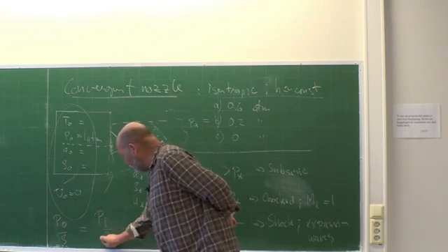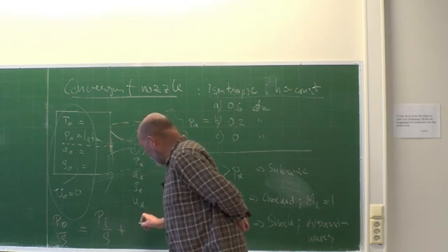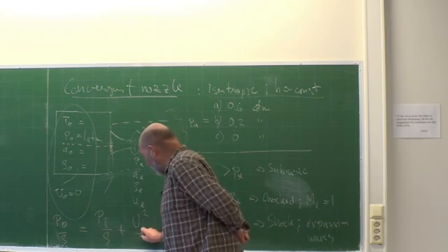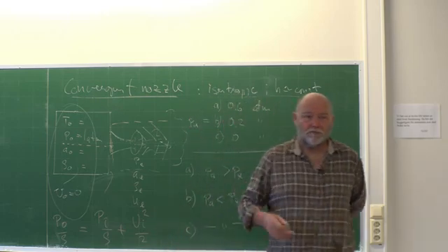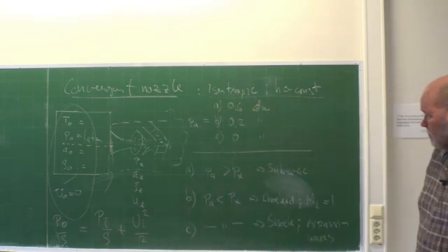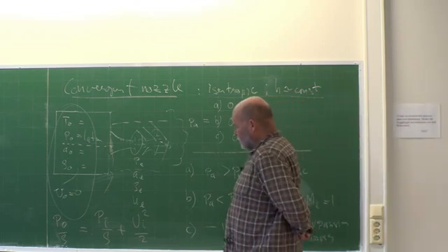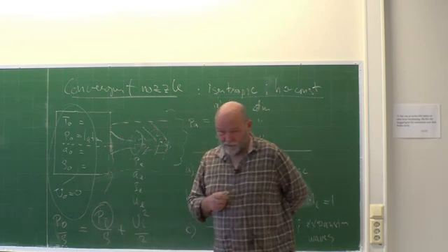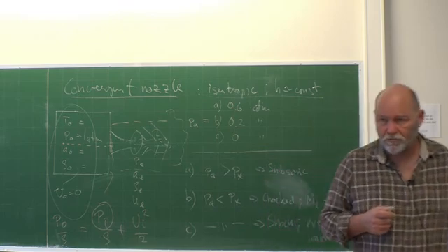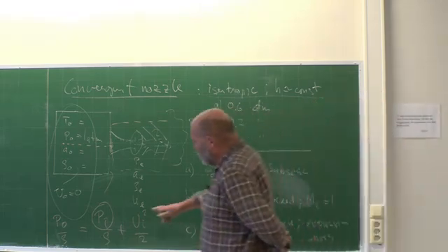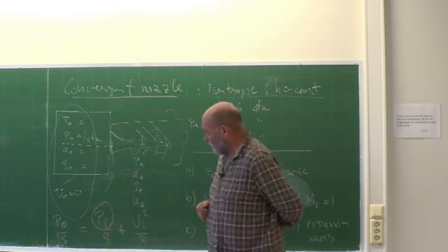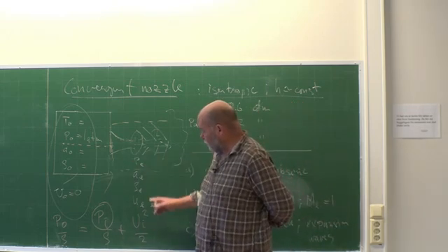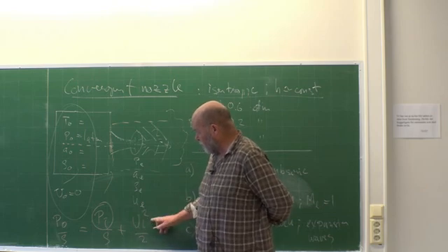Well, you will have this one, and then you will have plus the dynamic pressure, velocity at the inlet squared half, just the dynamic pressure. So there you can have a coupling setting up this situation. You have to give this value as an inlet, say a boundary condition for the pressure, but I would like actually to have this one, but we can't. And then the solution will provide us what this velocity will be.